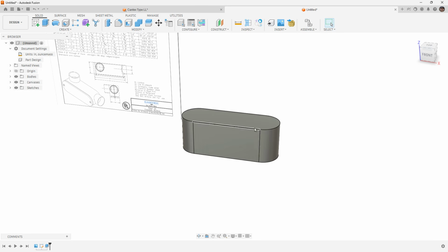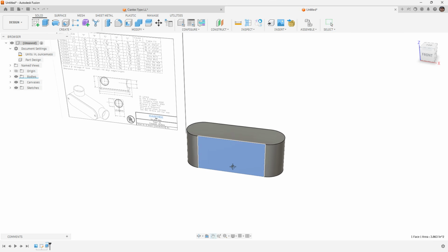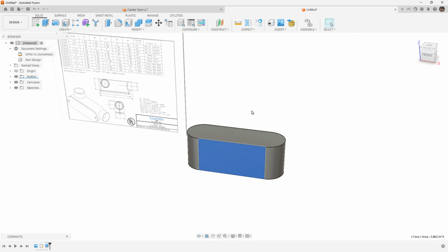And then we can start creating the geometry for those ports. And again, we need to be careful that we reference this geometry, noting that if we went above 2 inches, if we went to 2.5, that fillet would need to be gone. And so if I'm configuring a design like this, I'm thinking about all of the variations, all the dimensions that need to be configured here.